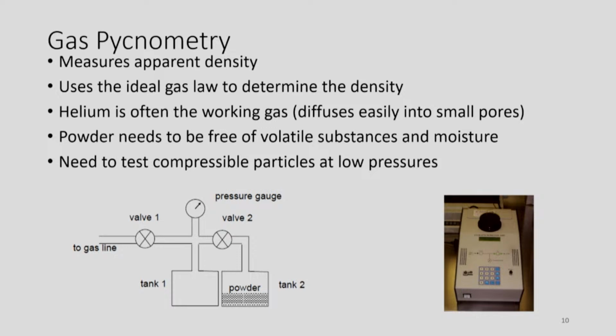The other common method, many of you would have used, is gas pycnometry, right? Any of you used gas pycnometry? No? So it's very similar to the liquid method, but we are using gas. You pump gas inside these powders, and it's very similar to what we talked about with sorption, chemisorption and physisorption, right? The gas fills into the void spaces, both external and the outer voids between the intergranular void spaces, and then gets the actual volume of the particles.